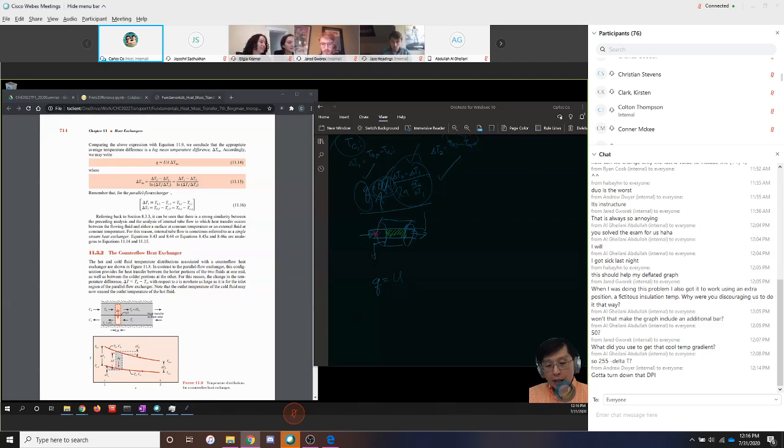So what happens? This is characteristic of your device. You might ask, if I increase the flow rates of the water in the pipes, does that affect the value of U? Definitely it affects the value of U, because it affects the heat transfer coefficients. But if I increase the flow rate, what is the biggest effect?